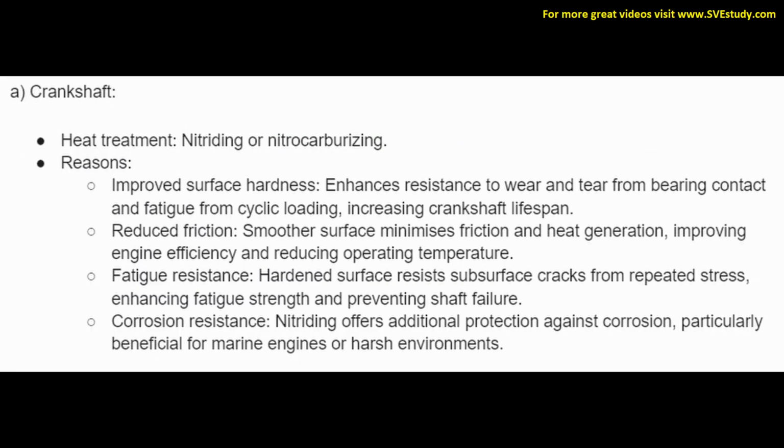A. Crankshaft. The heat treatment would be nitriding or nitrocarburizing, and the reasons: improved surface hardness. It enhances the resistance to wear and tear from bearing contact and fatigue from cyclic loading, increasing crankshaft lifespan. Reduced friction. A smoother surface minimizes friction and heat generation, improving engine efficiency and reducing operating temperature.